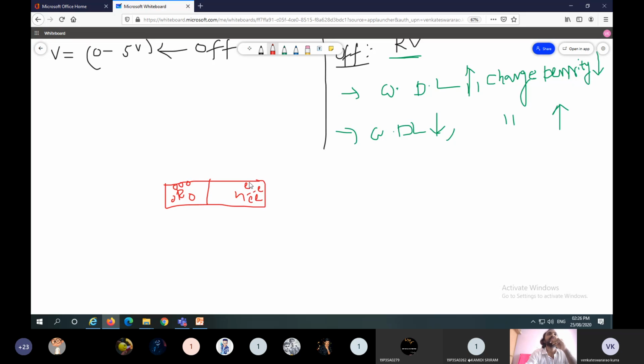Under normal operating conditions, the electrons near the junction diffuse to the p-type material, and the holes near the junction diffuse to the n-type material, forming a layer around the junction. Due to this diffusion of electrons and holes, some electric field or some negative voltage appears across this region. This is the barrier voltage.